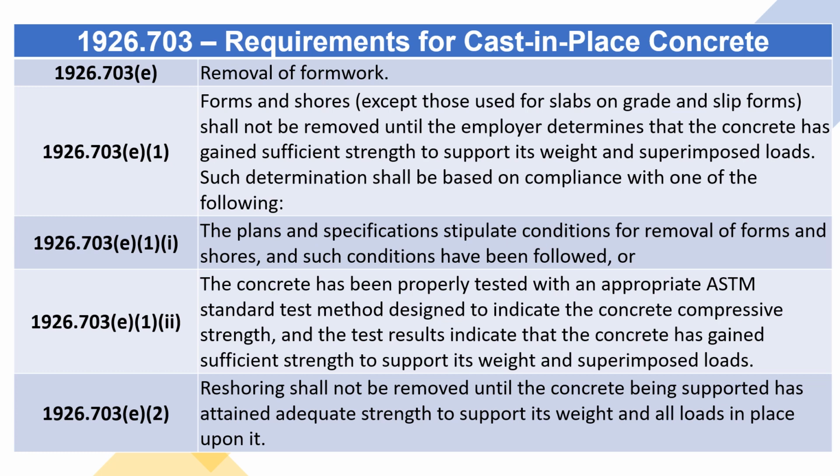1926.703(e)(1): Forms and shores, except those used for slabs on grade and slip forms, shall not be removed until the employer determines that the concrete has gained sufficient strength to support its weight and superimposed loads. Such determination shall be based on compliance with one of the following: